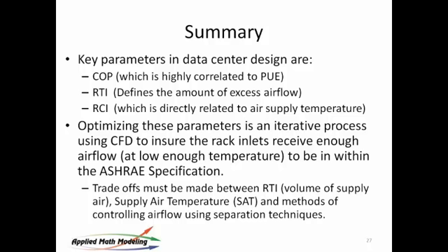Again, if it's a DX unit, use current probes. Your electrician will know how to do that. He'll give you current readings. You can very easily, therefore, just calculate what the power consumption is. If you're not familiar with those equations, I can supply them for you. Send me an email. Or look them up on a wiki. Look them up on Google.